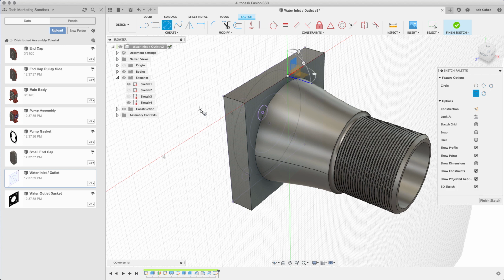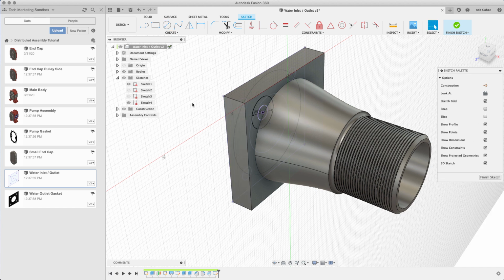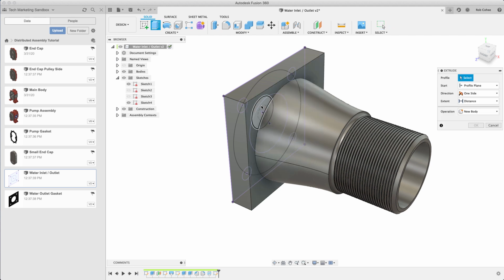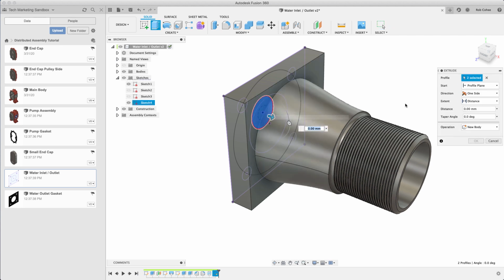So I've started a sketch on the front side of this. I'm going to use project geometry to bring my hole position where this thing mounts up. And what I'm sketching out here is just a 10 millimeter, a little bit of a relief cut. So I need access to place a screw here, but you can see where I need to place it, there's some material interfering.